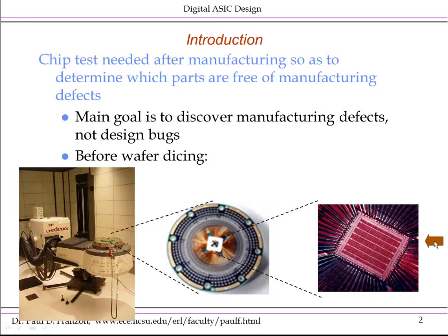And on the right we have detail at the chip level. Here all the probes in that probe card have attached themselves to the chip and are applying vectors through the pads and reading results from them. You notice how big the pins are that are accessing the chips. Because of their size, they typically cannot operate at high data rates, typically only something like 100 or 200 megahertz.